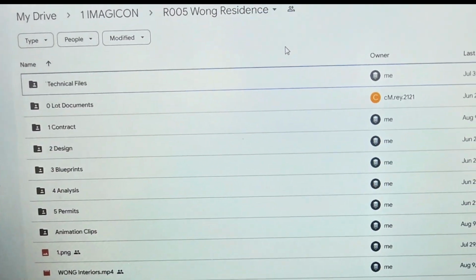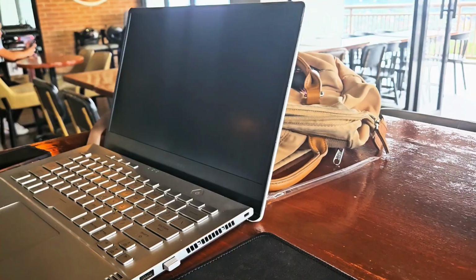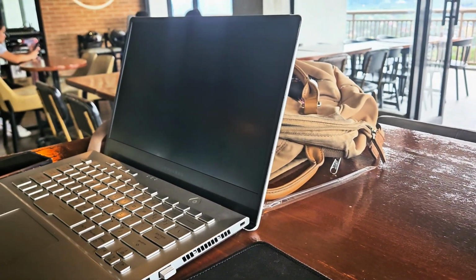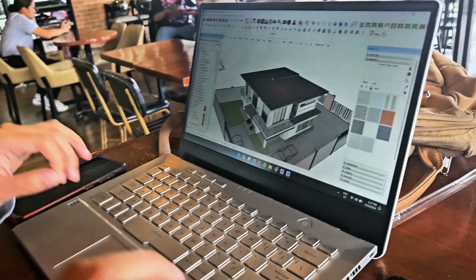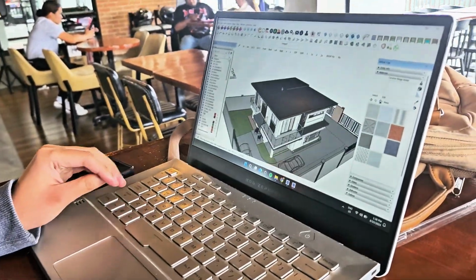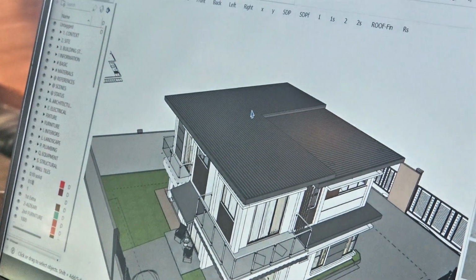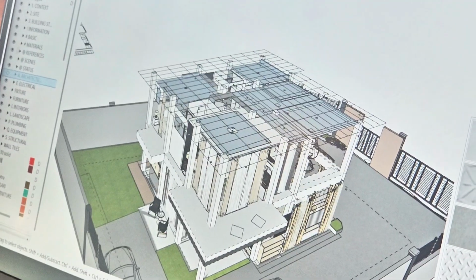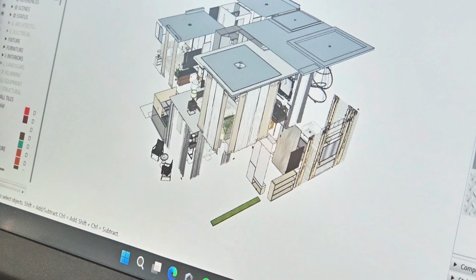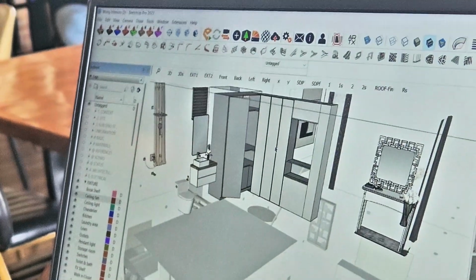See how organized our model is. If it's too heavy per floor, do it by room. If it's too heavy per room, do it by component. That's the technique. Because I organized the folders, just go to your tags on the left side. Turn off architectural, everything except interiors. Okay, more. Same thing only for carpentry.